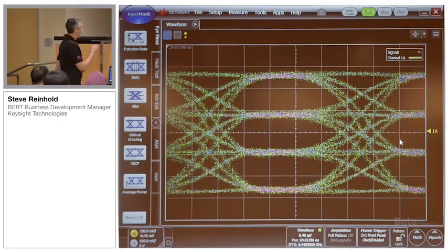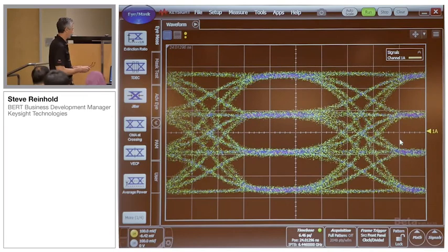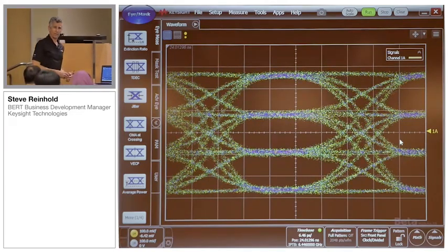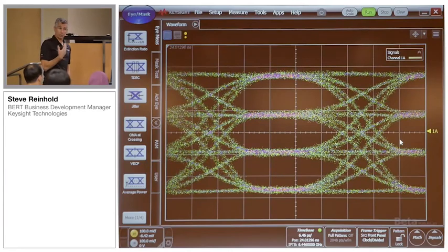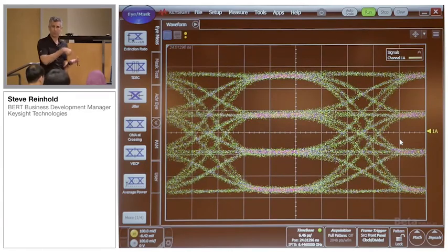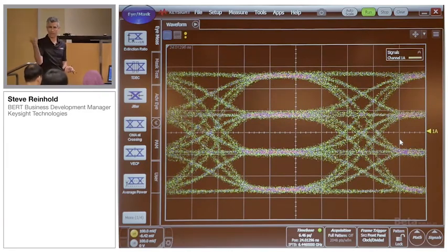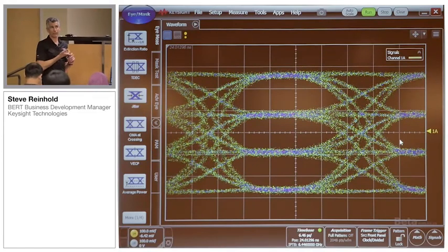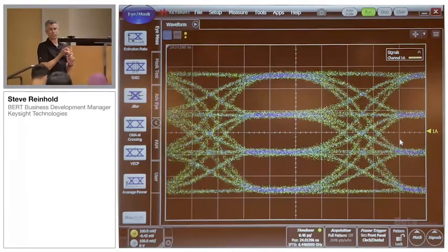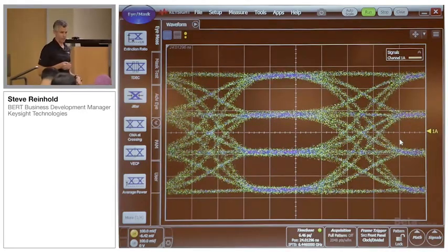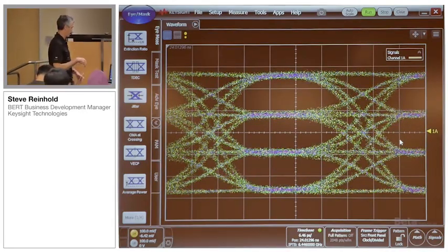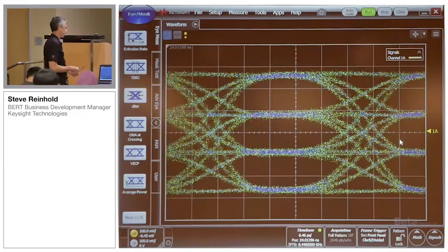I'll flip over and show you the GUI. We have patterns, again, up to PRBS 51 or user pattern. So if you're going to put in a custom pattern, your own pattern, or SSPRQ, we have 2 gigabits of memory for NRZ or 1 giga symbol of user memory for PAM4. So you can put some fairly long patterns into the pattern memory.